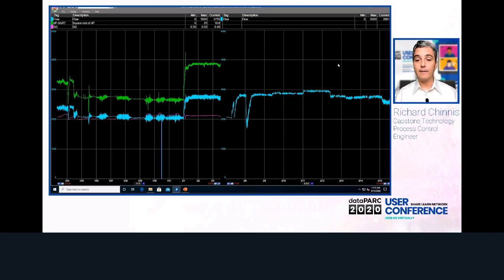On the right-hand side, I have the same flow tag, but for a different period of time. This will be the period of time we use to evaluate our model to see how good of a job we did at building a model. You can see the time frame here is January 24th to February 3rd, and on the right-hand side, February 8th to February 15th. It's very important to evaluate a model against a time period that is not included in the data set to determine if the model is valid going forward, because as time goes on, it will be using data that it never saw.